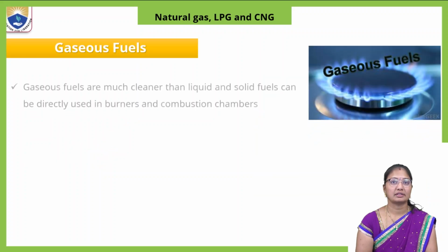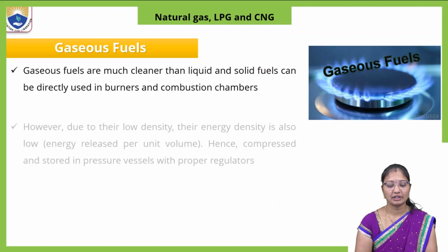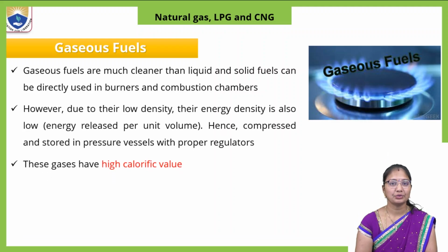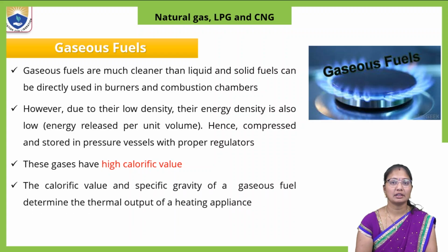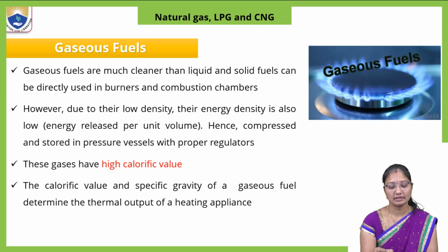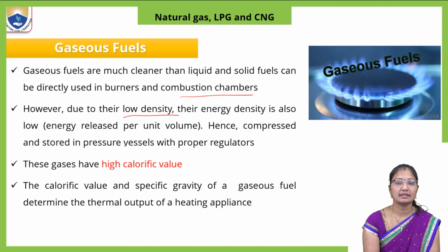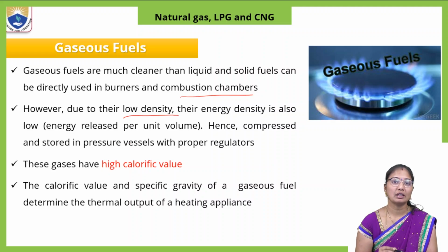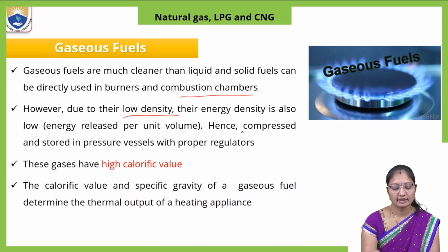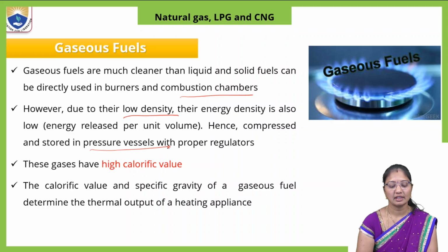So what are gaseous fuels? They are much cleaner than liquid and solid fuels and can be directly used in burners and combustion chambers. These are readily available and readily used in the specific burners and combustion chambers. However, due to the low density of these fuels, their energy density is also low. The energy released per unit volume will be low because of the low density of these molecules. Hence they are compressed and stored in pressure vessels with proper regulators.